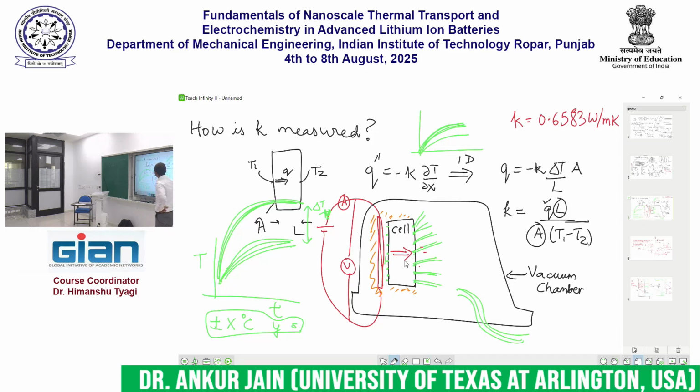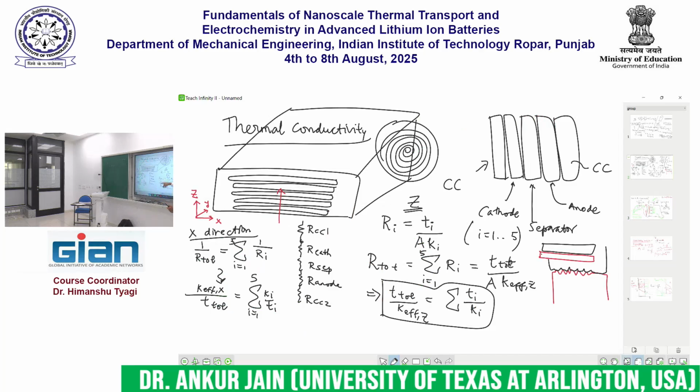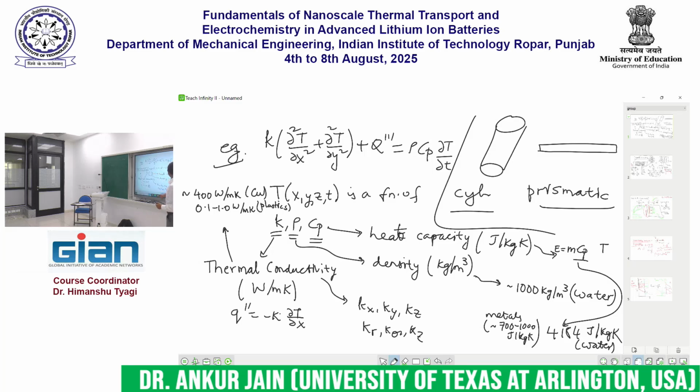Correct? It is being produced here uniformly. So the only way for it to go, and there is insulation on the top and bottom, the only way for it to go is in this direction. If I want to measure thermal conductivity in the other direction, I have to flip it over and apply heat on the Y face and force it to go along the Y direction. Right? So if I am interested in measuring the three components of thermal conductivity, X, Y, Z, then that requires three separate measurements. Okay?